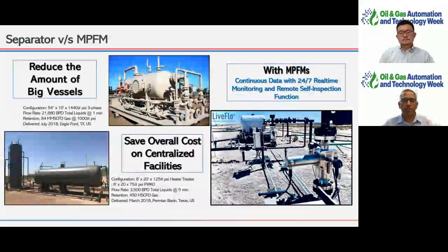So just to give it in a picture, and I guess most of y'all would have seen these pictures in the field, you can see the comparison when you look at the size of the test separator against a multi-phase meter. What we have in the lower right corner is the meter on a flow line, right at the wellhead. The difference in size, and in the actual capex and opex that go into the installation, is huge, because this is not a pressure vessel like the separator.